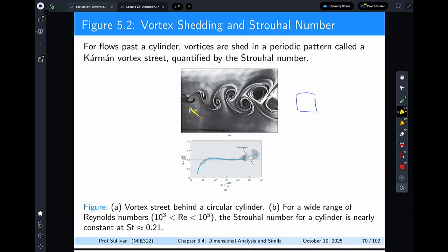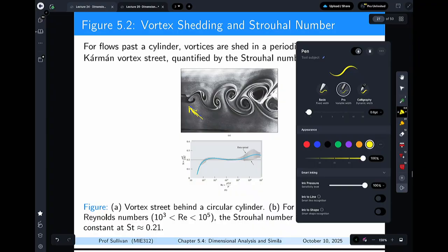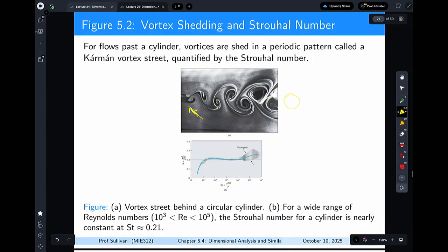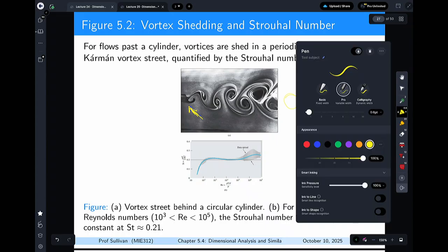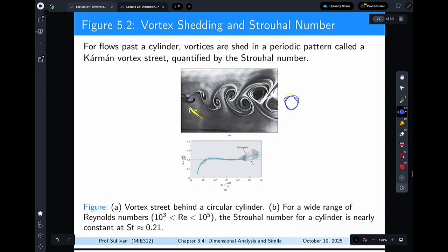And this is the Strouhal number versus Reynolds number. So, just to avoid problems. What you have is a wake, and as the wake develops, you have these alternating vortices that appear. Strouhal number, and one of the things that we've spent a lot of effort on, and this is about a century of looking at flow past cylinders, is identifying these regions.